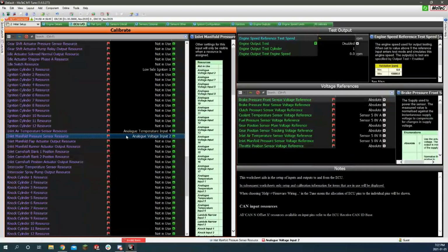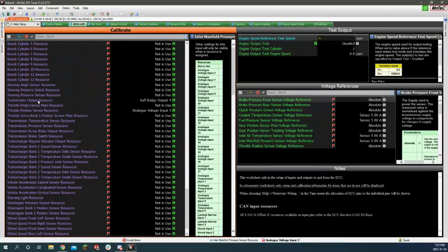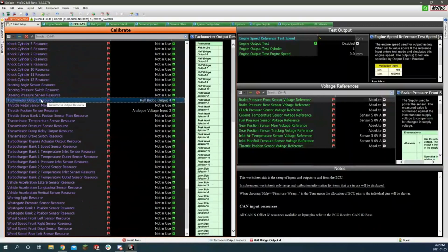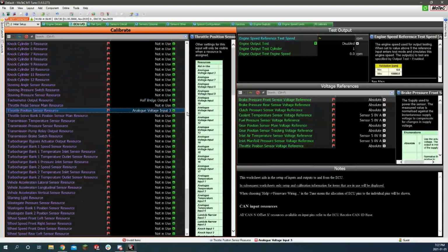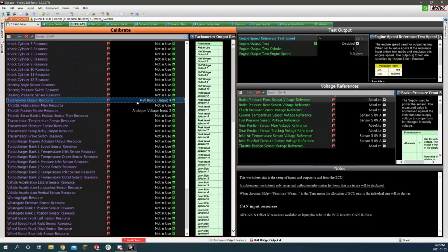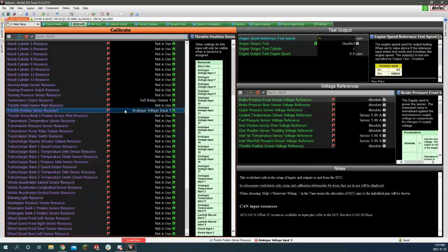Then when you're at full throttle, it should be at about 100 kPa, which is about what the atmosphere is. So knowing that, you know how much air is going into the engine. That's just a tach. We can output a tach to shift lights, whether that's integrated into a dash or if we have standalone shift lights.